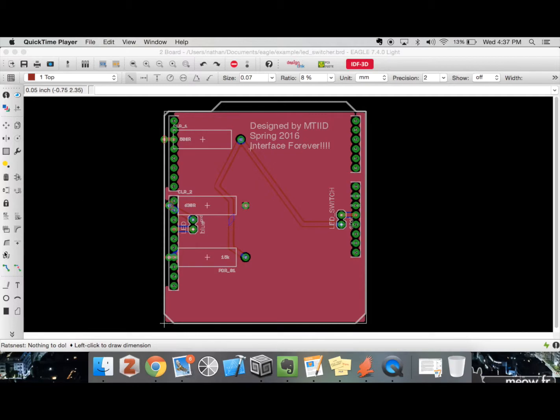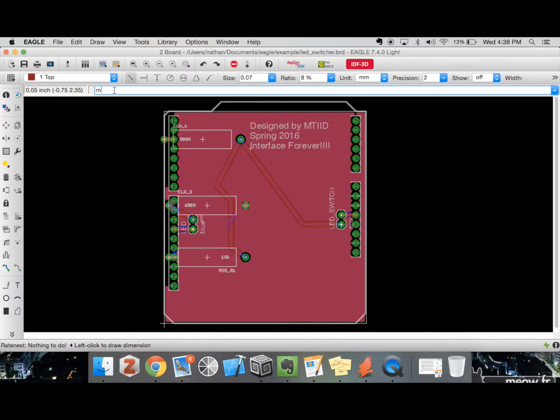So the next tool that we have is the meander tool, and meander is a very interesting tool. The idea of meander is that you enter the name meander, and you also give it a length in inches. Let's say we're going to do 5 inches here, and you press enter, and then you click on a net segment, so a straight line. It says what our goal is here, 5 inches, and it also gives us 30.2%.